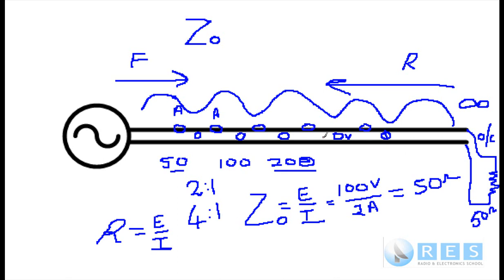We try, with coaxial cable in particular, to terminate the cable into 50 ohms to avoid standing waves and to avoid extra line losses. And don't let anyone else tell you there's anything else bad about standing waves. There are a whole hodgepodge of fallacies regarding standing waves, such as the reflected power comes back and jumps into your transmitter and burns out the finals. Standing waves cause interference. There's a whole raft of fallacies regarding standing waves.